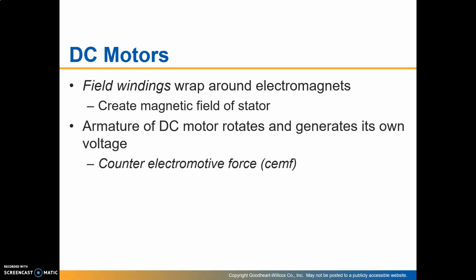When the motor is completely stopped, that's when it's really going to draw the most amount of current it can draw until the motor gets up to speed. With a DC motor, as you load it and slow it down, it'll draw more current to try and speed up and generate more torque to match that load that's being drawn on it.